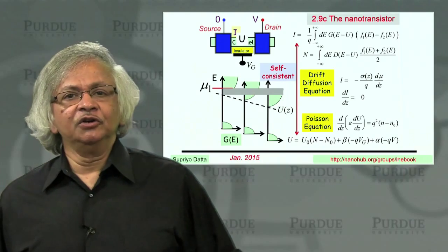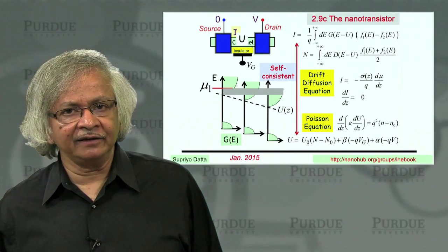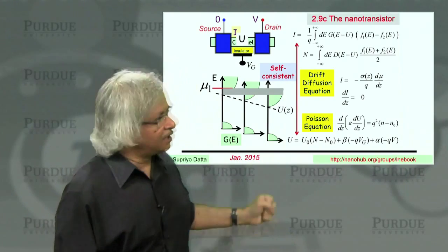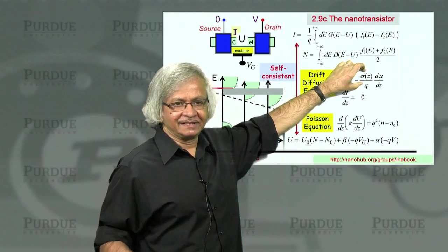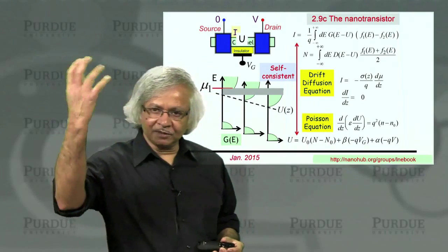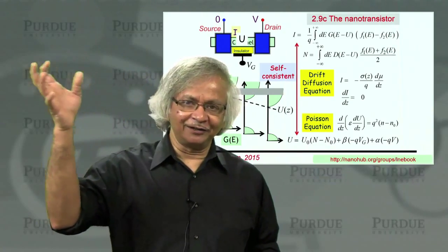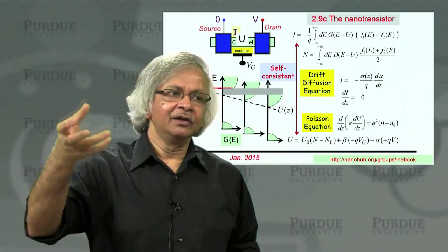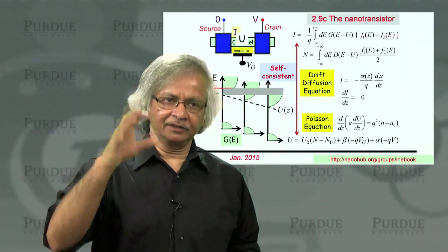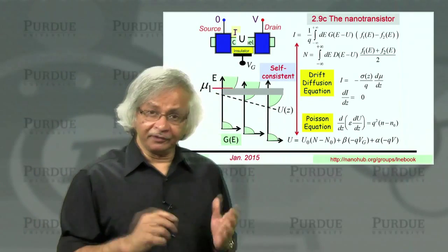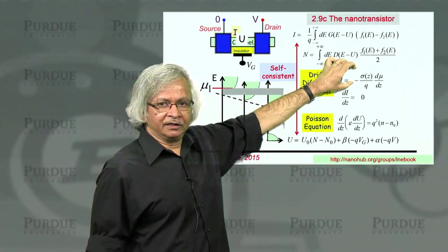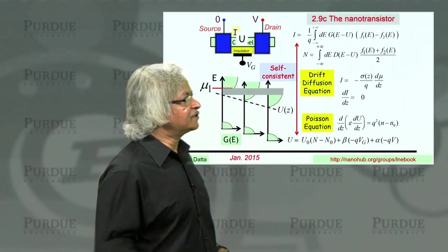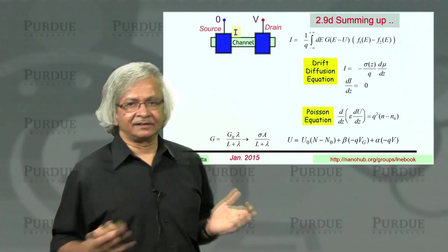So what did our new perspective add to this whole thing? Well, what it added was a different way of understanding the sigma. As I mentioned, the old perspective is sigma is q squared n tau over m, the Drude formula, whereas we had a way of thinking about it which I believe is more direct. But more importantly, it also gives you this extra thing called the ballistic resistance.